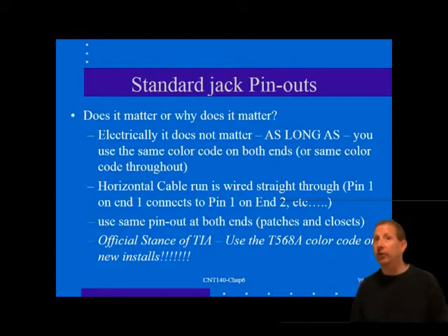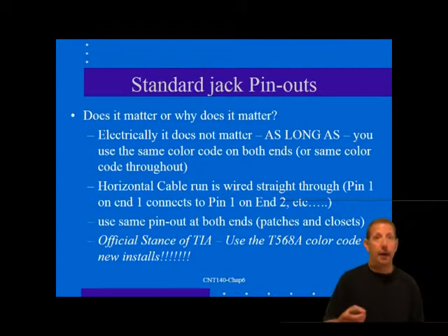These certain systems are the ones that already use the optional pattern for the most part. If you do not need to connect to an existing cabling system that uses 568B, you should use the recommended A pattern. So what difference does it make which pattern you use, A or B? Electrically, it makes no difference as long as exactly the same pattern is used on both ends. So let's say that again. The two patterns are electrically equivalent as long as both ends of the cable are wired with the same pattern.